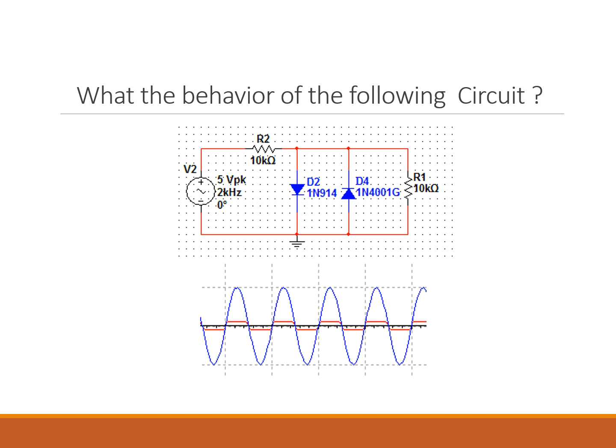So just to summarize the behavior, the limits for this signal are going to be between positive 0.7 volts and negative 0.7 volts. Anything outside this window is just chopped off. And this is a good symmetric clipper around 0 volts. A good application for this would be input protection, amplitude control, signal shaping again, as we mentioned before.